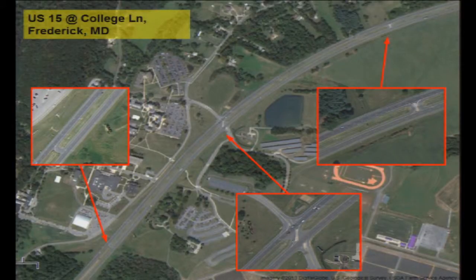Okay. And this is a real intersection in Maryland. This is what you see. They use this as a corridor treatment, and the main intersection will look something like this. So the minor traffic will not be able to go through the intersection. So they enter it, do a right turn, and then come back through a U-turn, something like this. And this is a corridor treatment.